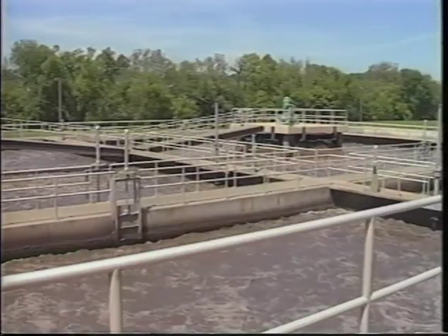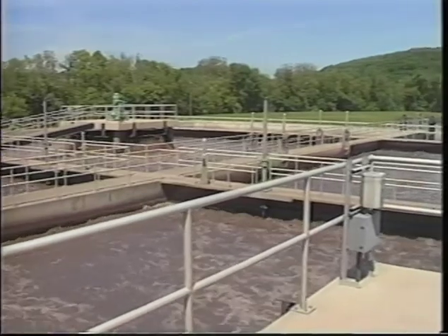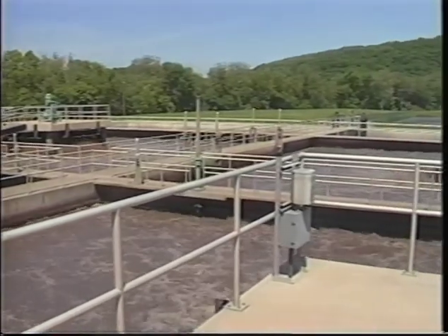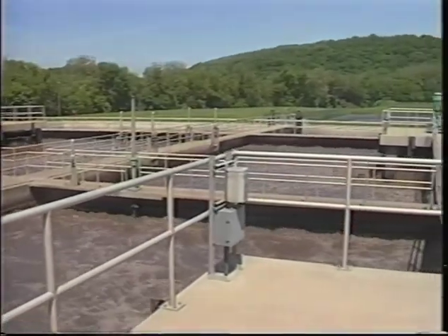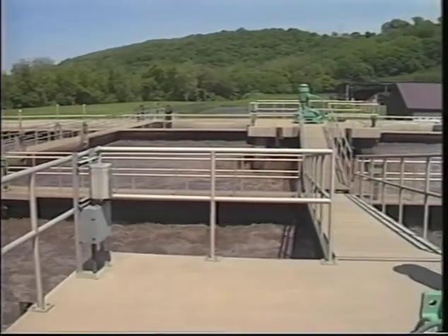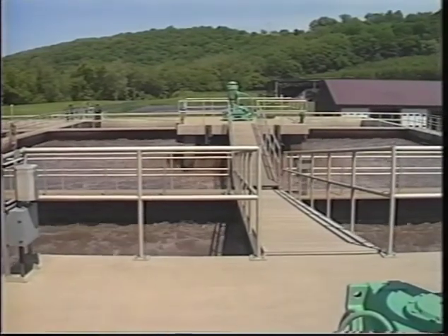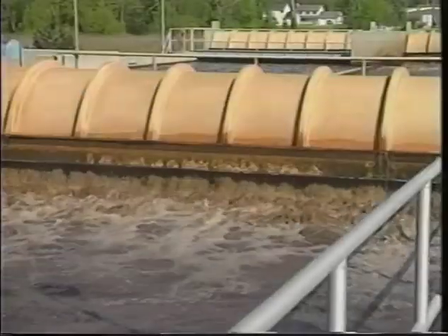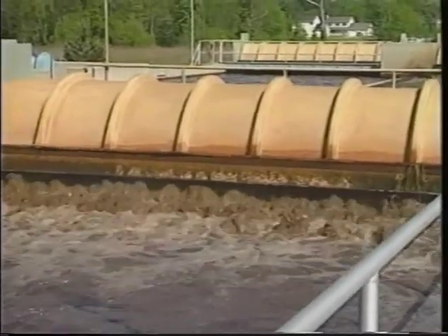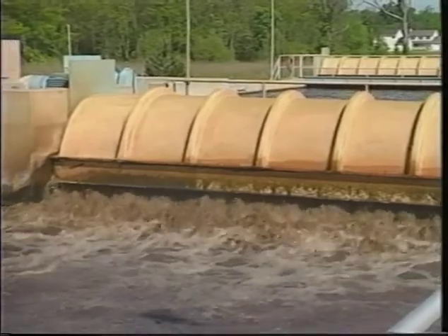If you divert the return activated sludge to the tank inlet and the influent towards the latter 2/3 of the aeration tank, you are operating in the contact stabilization mode. With this flexibility, you may be able to treat peak flows or higher loadings at your facility in the contact stabilization mode.